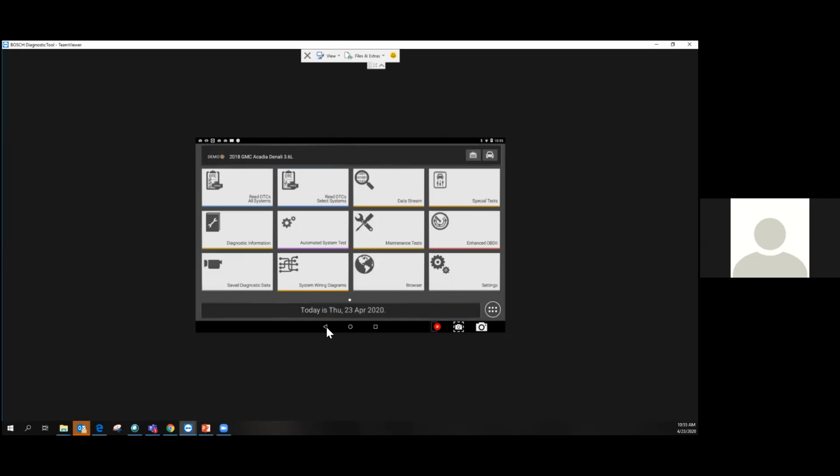Well, then I'm going to go into that parking module. I'm going to watch my data stream. I'm going to see all 4 of those sensors, and see what distance it's reading on each one, and I'll be able to pinpoint which sensor is giving me that incorrect reading, either because there's nothing back there, or maybe I just go stand behind that sensor. Does it read that there's an object right there? And I can test each one of those sensors one by one.